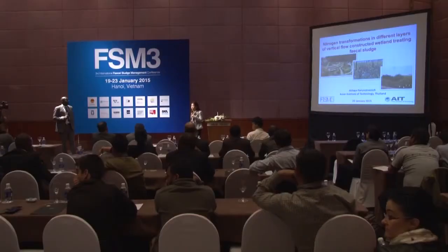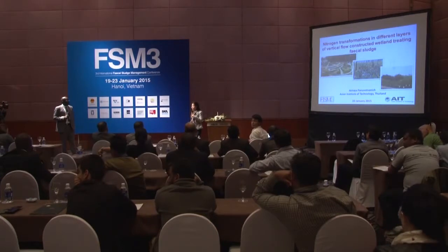Yes, actually, in our previous study, I also tried to increase the depth of the sand layer. That can increase the efficiency of the nitrification reaction, but it may reduce denitrification, so you may have a lot of nitrite and nitrate, which is not removed as nitrogen within the system. But it depends on your purpose. If you would like to reuse the nitrogen, it's also quite good if you increase the depth of the sand layer in the system.